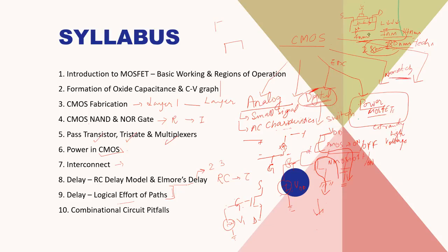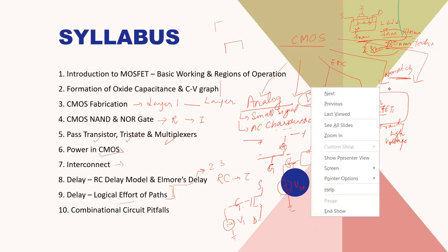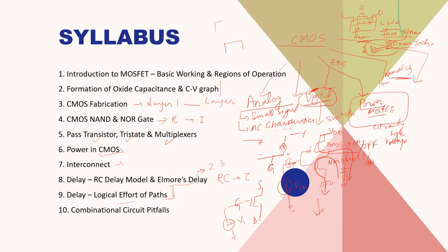When you're reducing channel length, what are all the different phenomena that MOSFET is going to suffer? MOS is going to have a supreme amount of leakages as you reduce the channel length. There will be different short channel effects. If somebody has studied this term, short channel effects, for example, drain induced barrier lowering, there are around 5 or 6 effects called short channel effects which start occurring once you reduce the size of these devices.